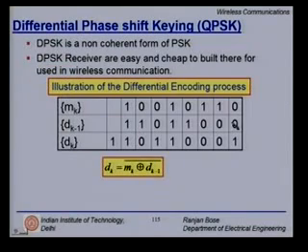So you have your message m_k, these are bits clearly, and then the differential output is represented by d_k. And here we have written down d_(k-1) and at the kth instant d_k. So if you look, if there is a 1 here, there will be a 1 here, 1 here, 1 here, 0, 0. So they are just shifted versions of each other. So the d_(k-1) row is shifted to the right with respect to the row of d_k.